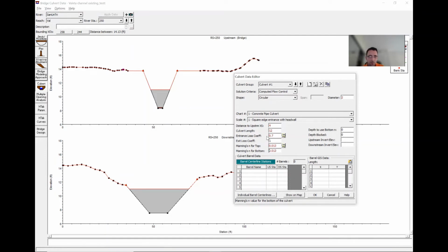So now I have only some information about the characteristics, not about the geometry. So if I want to show upstream, you basically need to have some elevation for upstream. This is about 8 and this is 9, so you can show it's between 8 and 9. What I have here is 8.3 for the invert of the culvert, 8.3.